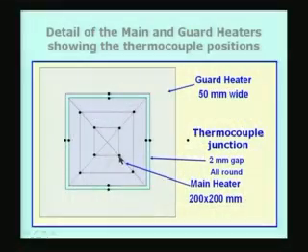Therefore, the assumption we can make is that the temperature of the surface of the heater and the surface of the sample which is in contact with it are exactly the same, so that when I say T0 in the expression for thermal conductivity, we had T0. T0 corresponds to the temperature of the heater, and TL will correspond to the temperature of the cold surface, which will be the same as the temperature of the surface of the sample which is in contact with the cold surface. So, that is the reason why we have so many thermocouples, and we measure, as I indicated, delta T across this gap must be equal to 0. So, the heat input to the guard is adjusted so that delta T is 0.